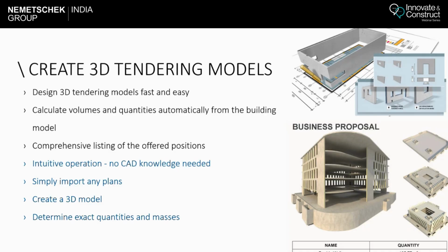With this, we can get how many double walls, sandwich walls, hollow core slabs, and columns are required, so that once my tendering model is done, it gives a tendering quantity which is fairly accurate because it has been created in 3D. Generally for hollow core, we need to know how many square meters are required.